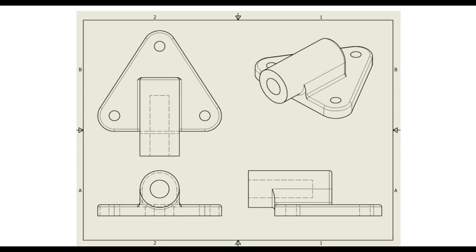Just keep in mind you should have Technic font. Your font placement should all be neatly placed. There should be no crashes with the font or too close to the edges. Make sure that you include the thread note for the whole depth here and all your center marks and center lines, a parts list with a bubble number, and the correct dates.